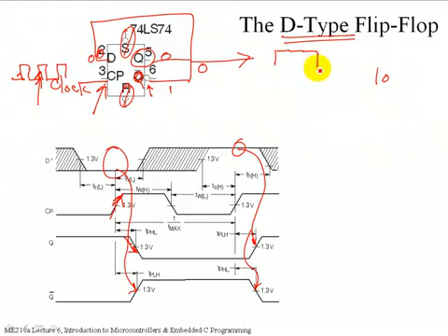So what happens is, if you think of it in terms of frequency, I just did a divide by 2. At whatever f I have as the input clock rate, if it's coming in at a regular rate, I'm going to have f over 2 as the frequency on the output.